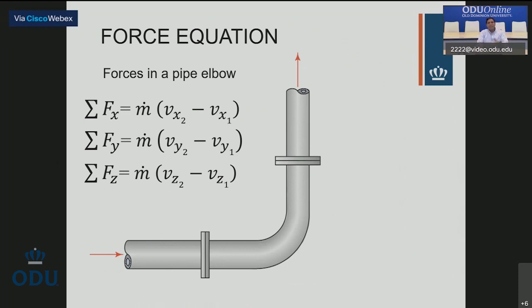Okay, let's apply the force equation, or the momentum equation, because now that Luis brought up the conversation, this is also the momentum equation. So let's apply those equations to an elbow. What happens is that when the water goes into this elbow where the flow turns, as you could imagine, that flow will push the elbow. And indeed, the elbow will feel a force, okay? It's being pushed. Now, because of another of Newton's laws, we know that the elbow will counteract because of the action-reaction law, Newton's law, right?